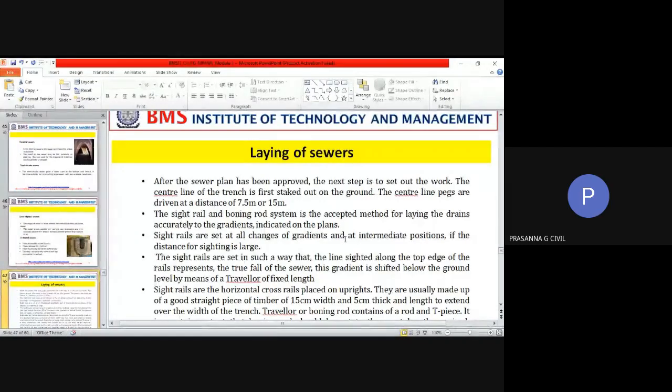So the direction of flow has to be towards where the branch sewer is, on the sub-main road or something like that. If you are laying the pipe perfectly horizontal in between the area of the sub-main and where the buildings are, then there is every chance that the sewer will get clogged because there is a lot of dense, heavy material in your sewage.